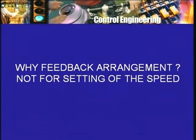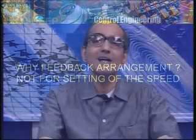Now, the reason for using feedback was not really all this, because the operator could directly control or set the field current at the desired value so that the motor runs at the 1500 rpm speed. So why have you bothered to produce all this feedback? Now any system, any control system, whether regulator type system, whether manual or automatic, has to have a set point input if it is to be capable of running at different constant values of the output quantity.